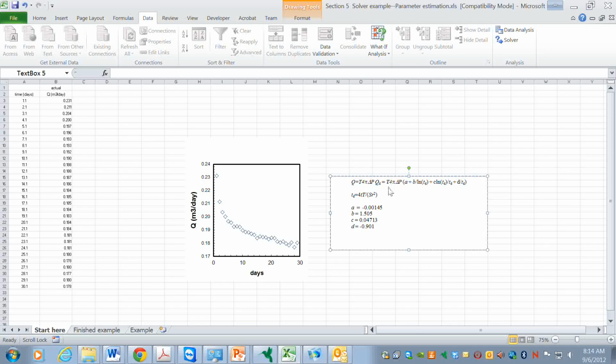So that's the transmissivity of the well, T. Delta P is the drawdown that's held in the well. And A and B and C and D are constants. And this TD term is right here. This is the dimensionless time, and you can see t there, that's the actual time, and then the transmissivity, there's the storativity, and r squared is the radius of the well, and they're the constants.